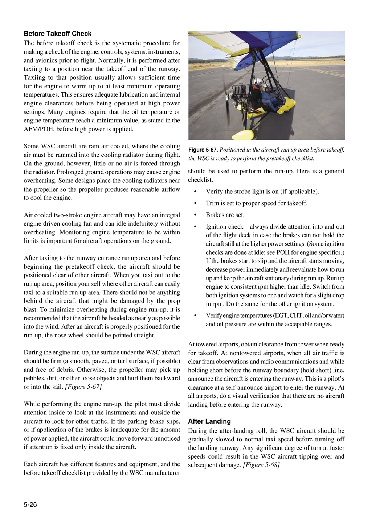Before takeoff check: the before takeoff check is the systematic procedure for making a check of the engine, controls, systems, instruments, and avionics prior to flight. Normally, it is performed after taxiing to a position near the takeoff end of the runway. Taxiing to that position usually allows sufficient time for the engine to warm up to at least minimum operating temperatures. This ensures adequate lubrication and internal engine clearances before being operated at high power settings.